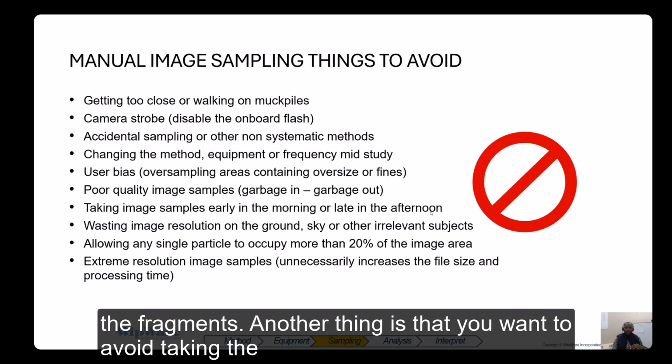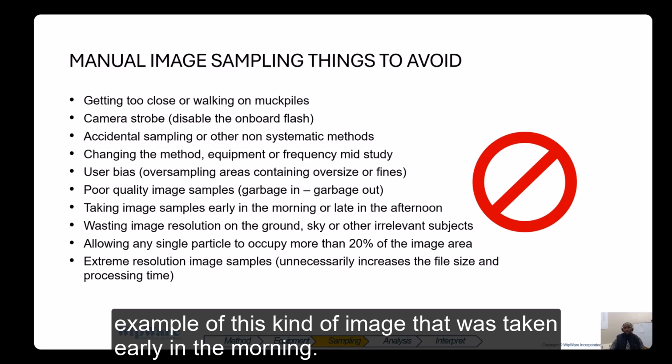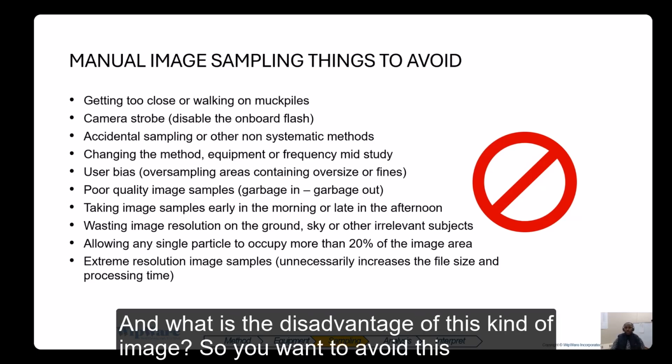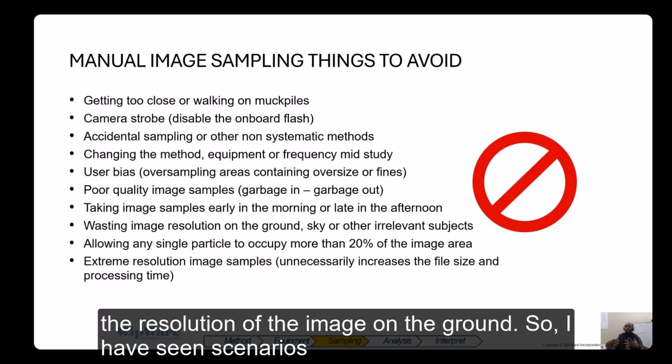Another thing is that you want to avoid taking the image sample early in the morning or late in the afternoon. I'm going to show you an example of an image that was taken early in the morning, and what the disadvantage of this kind of image is. So you want to avoid this scenario, and you want to make sure you don't waste the resolution of the image on the ground.